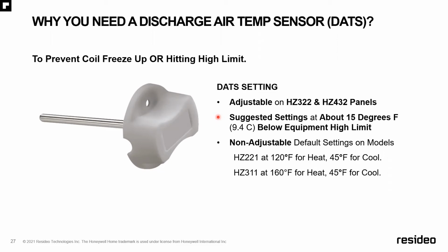Because when the furnace goes into a hard lockout approximately 4 or 5 times, now your customer's stuck with no heat until somebody typically trips the circuit breaker to reset the furnace so that it can get back online. This is why having your hands tied with our 311 panel makes it extra prone to perhaps some service calls.